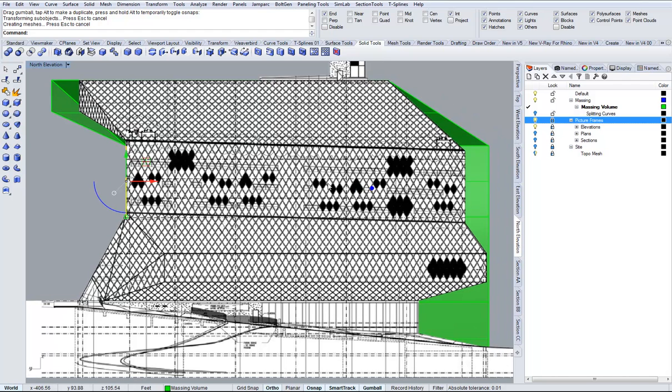You could definitely split the faces accurately with this tilt. But if you do that, it's going to create more complicated faces with more ISO curves. And after we do a lot of these kinds of moves, it tends to produce a lot of extra curvature in the surface, and we don't want that. It's a little easier to just make all the faces you need and then move the faces and edges accordingly, and it'll keep everything flatter and cleaner.